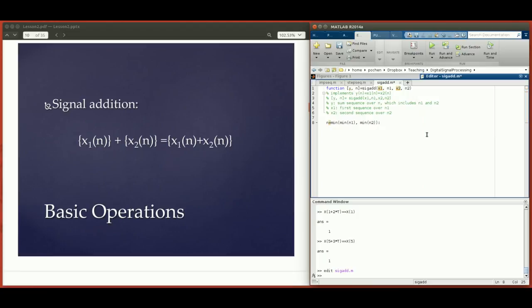Colon. I'm still going to assume that the stride is 1 for every sequence. If the stride is not 1, if it's some floating point number, for example if your sampling interval is like 0.02 seconds, that can be easily adapted by just multiplying a constant. In practice, you never have to worry about that. In your signal processing routine, you can just assume the stride is 1. Any kind of stride that's a floating point number can be easily adapted. You don't really have to change your processing code at all.